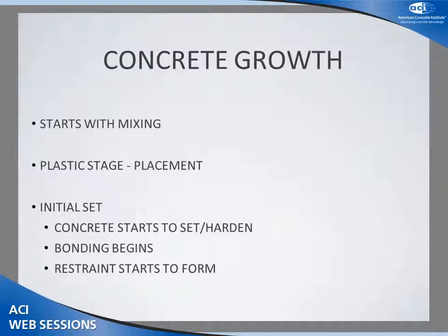When concrete shrinks, it goes into tension. Concrete, particularly fresh concrete, is not very strong in tension, and when the shrinkage forces exceed the tension strength of the concrete, shrinkage cracking occurs. Shrinkage-compensating concrete expands during the early stage of curing, and when it goes into its shrinkage phase, it shrinks by counteracting the expansion.